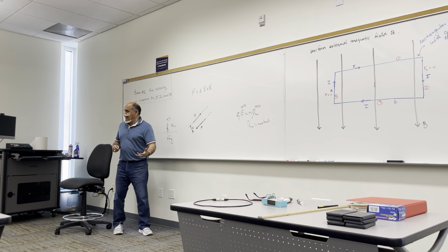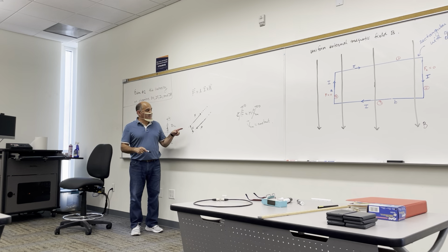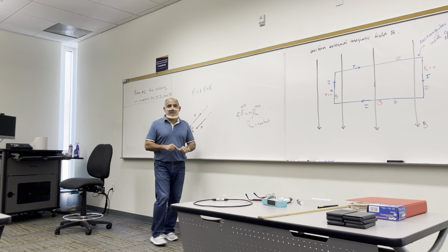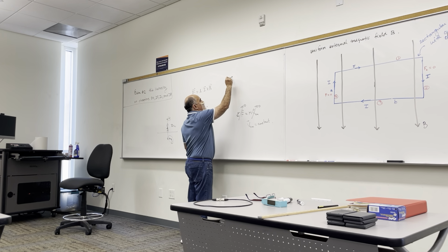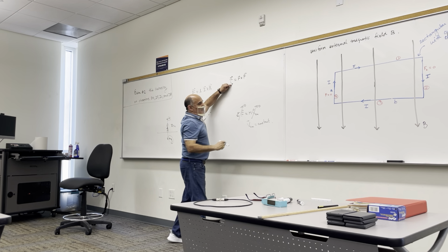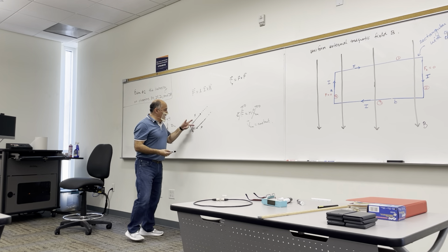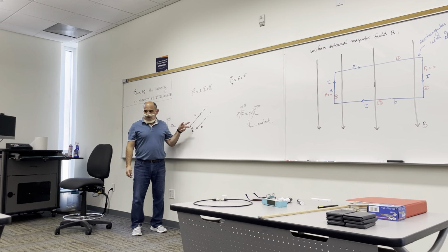And there's a Hoover problem where you calculate the torque of a couple. When you calculate the torque of a force, it's R cross F about point P, so it matters about what point you take the torque about. But when you have a couple, the torque exerted by a couple is independent of where you take the torque about.